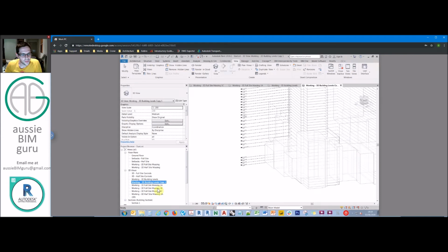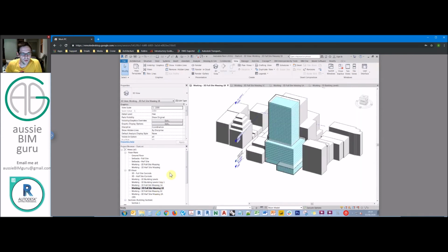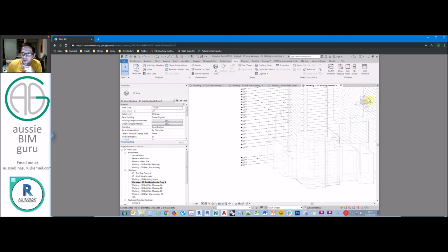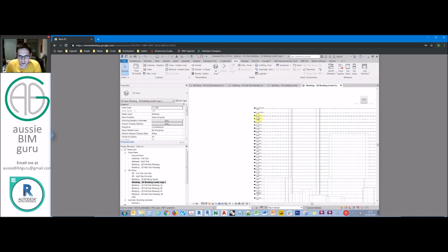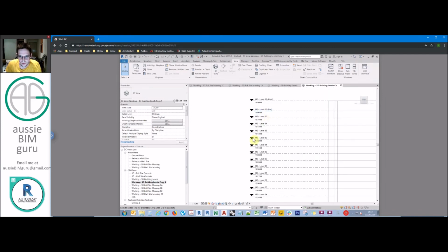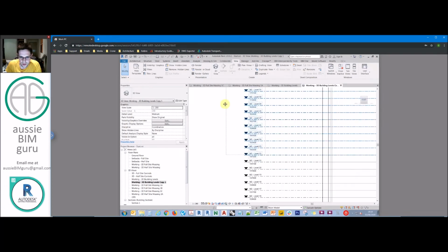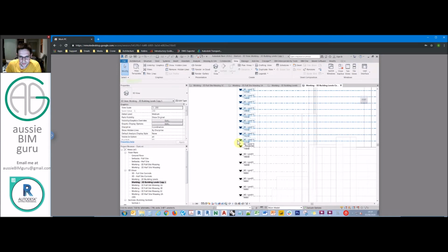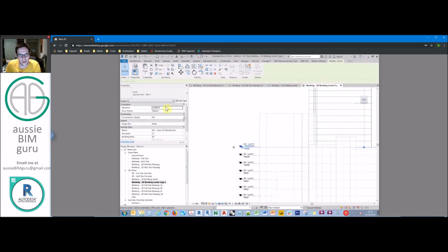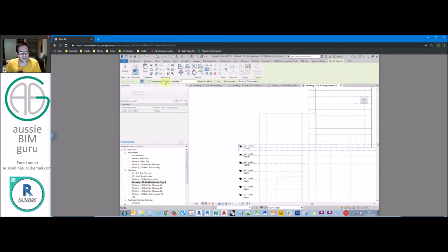Anyway, all we have to do from there is review, actually first we should review the levels in order to redistribute them into a 4 meter spacing. So I'm going to go all the way back down to my residential level, and I'm just going to delete all the levels until that point, because at this point our program changes. So what I really want is I want this to just be called level 10, and we're going to array this level, and we'll just array it maybe 20 times up by 4 meters.